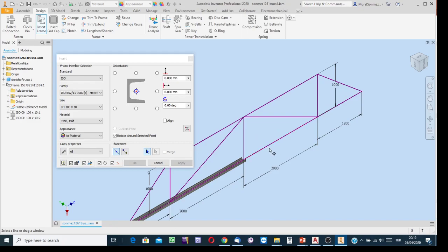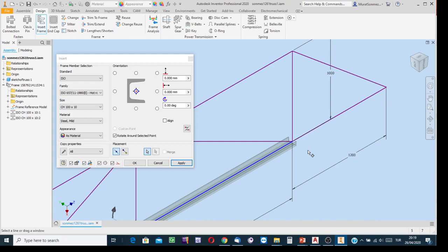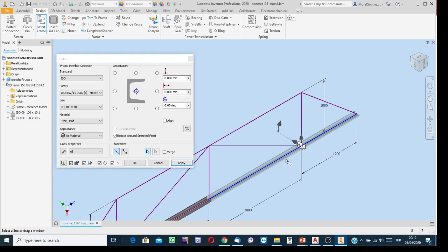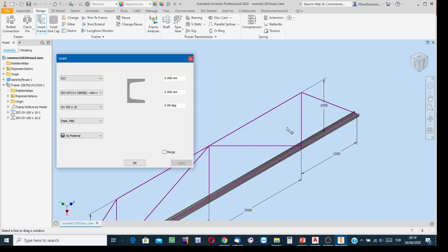This one, yes, correct. Or I said that I don't want to take a risk, but say take a risk, yeah. Try this one. Yeah, it is great. I am lucky. The orientation is correct. But I don't want to take a risk for the other. So after having the simulation for 2 successive members and seeing that these are in correct orientation, I don't want to take the risk one more time or further. Click the apply button and then say OK and then continue.